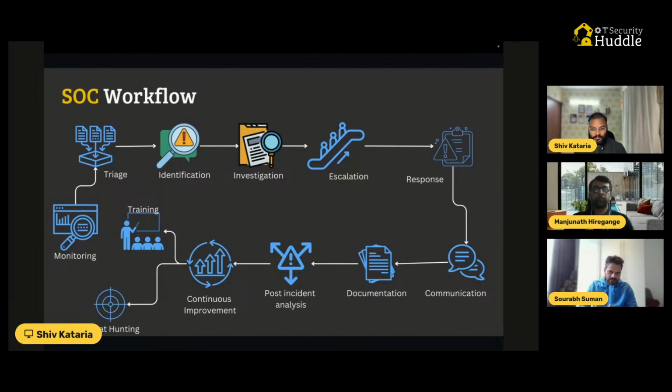They also should know how a thermocouple works, how an RTD works. Basic knowledge they should know. Then for the response part, I think that is more important, to know at a process level, at DCS level, if you have a DCS or PLC network level, what your network looks like and what type of communication is happening, what your time sensitive networks are, if you have a PIN network, if you have a PC LAN network in your SIS systems.